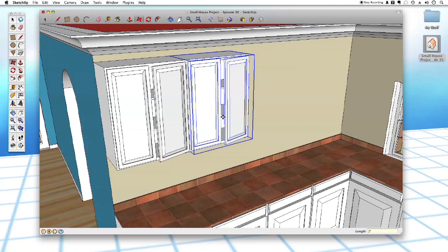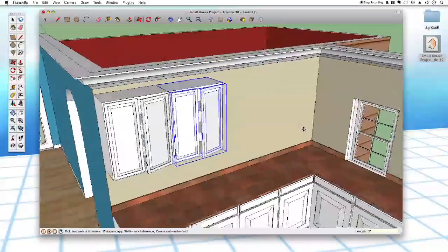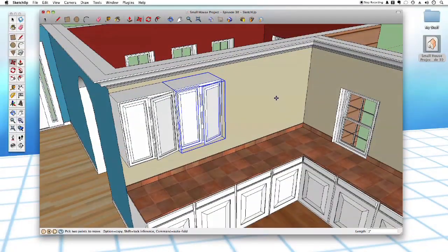Now, you'll remember a few episodes back we talked about multiplying and dividing, where if you've just copied something over, immediately after you've entered the custom value, you don't deselect or click anything else. If you hit either the star key or the slash key, you can multiply (star key) or divide (slash key) copies of what you've just done.